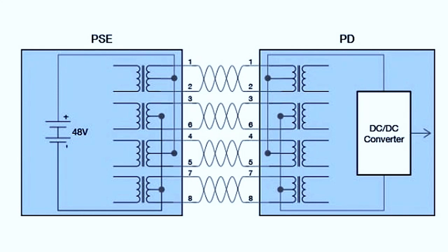Now the big problem comes in when we have more current flowing over one conductor of that pair than the other. When we don't have proper strain relief and proper connections, we end up with a resistance imbalance, and that causes more current to flow over one of the conductors. Big deal? Yes. Because now more current's flowing through one side of that transformer than the other, and that causes a saturation of the transformer and it causes data loss.